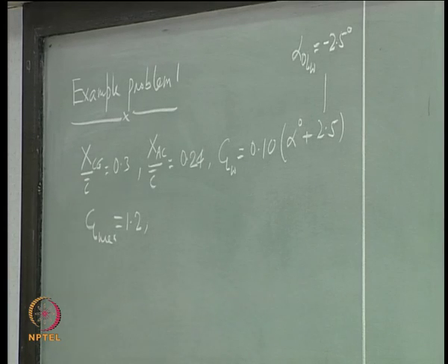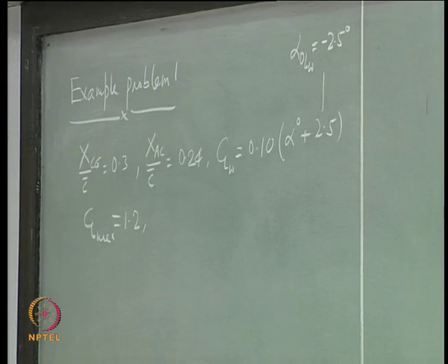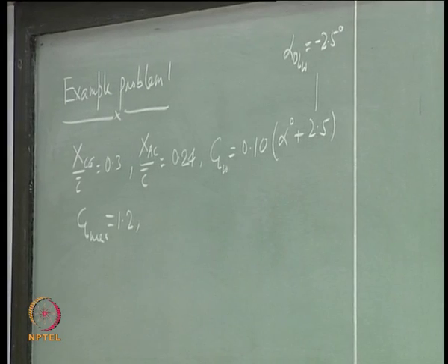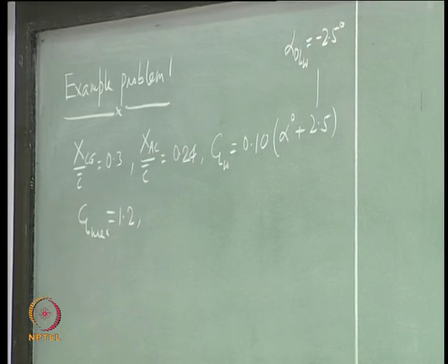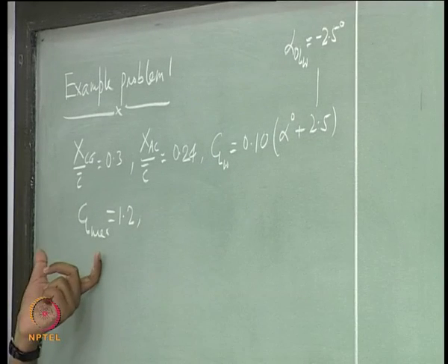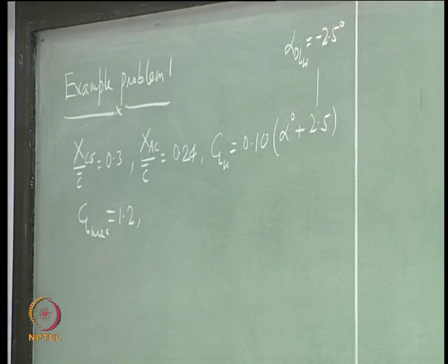So, we talk about CL of the wing, right, and this CL max you get when you have maximum elevator up deflection, right, because you are trying to move the elevator up and aircraft is pitching up, is not it. So, this CL max is corresponding to the delta E max that is given to you.